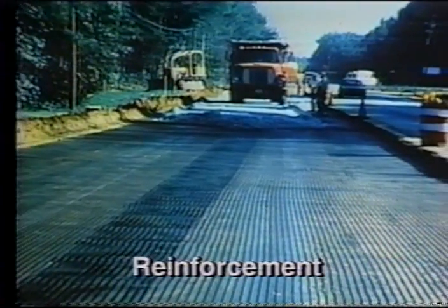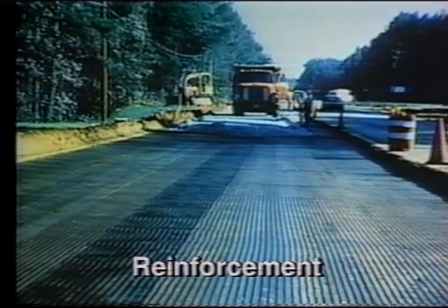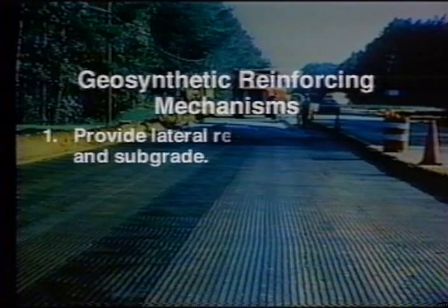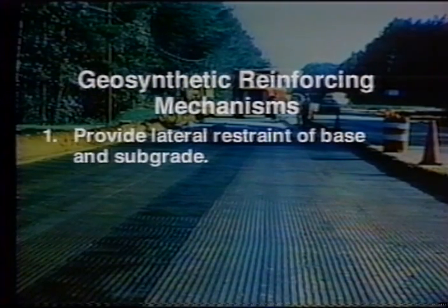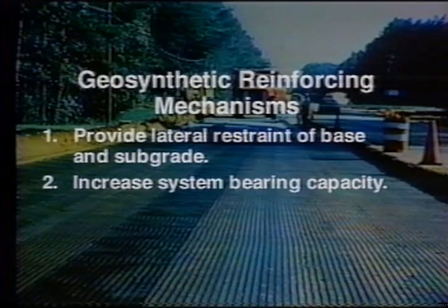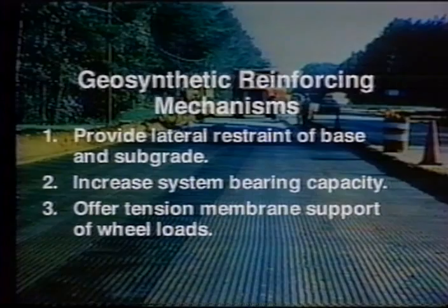Geogrids and geotextiles provide base reinforcement through one or more of these three reinforcing mechanisms. By providing lateral restraint of the base and subgrade, by increasing the system bearing capacity, and by offering tension membrane support of the wheel loads.